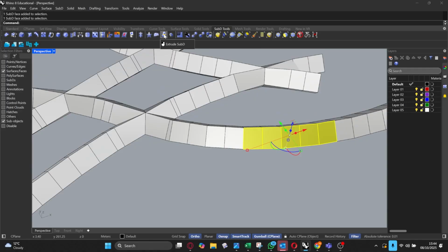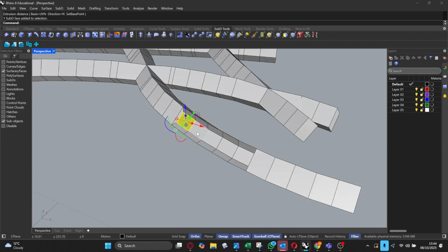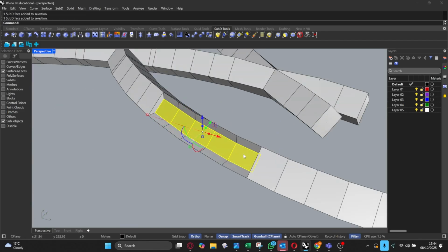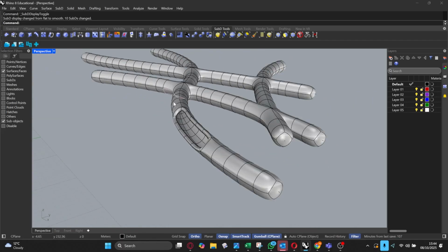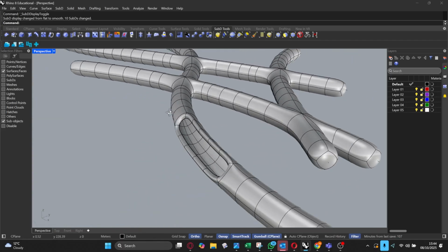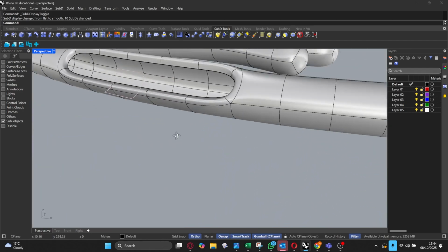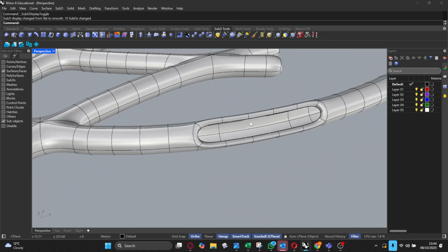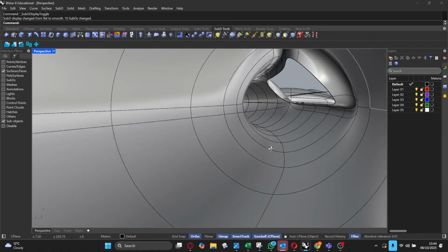Well, what I could do is extrude them, sorry. If I wanted to extrude them, I can start to extrude them inwards, for example, and then take the faces that I've extruded and delete them. And now if I go back to tab mode, you see that I've been able to create these openings now in my facade.